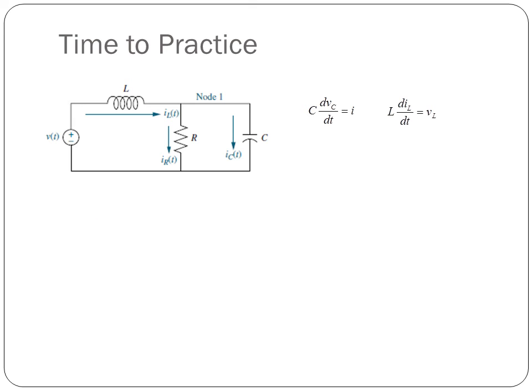That will be our state equation. We'll see in this example. So for a circuit, if we always follow these rules, that for a capacitor the voltage can be the state variable and for an inductor the current can be the state variable, this will be the easiest way to start your math. Okay, this is the easier start, but you can do it otherwise, no problem, but this is the easiest way to start. So for capacitor we will assume the voltage is the state variable, for inductor we will assume the current is the state variable.